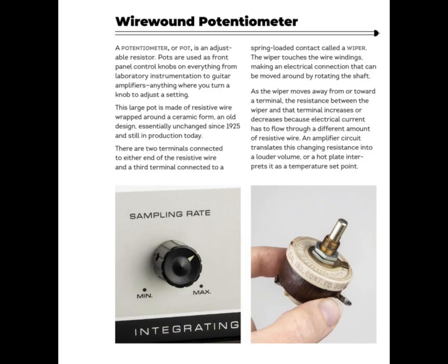In this case, the wire between two successive turns is not covered by the slider, which limits the resolution of wire-wound potentiometers. However, the larger the number of turns of the coil, the more the resolution. The resolution is measured as the reciprocal of the number of turns of the coil. Now, the advantages of this potentiometer are high power, high heat tolerance, very long life, and low noise.